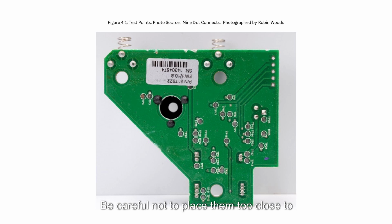Be careful not to place them too close to the solder pads of the device, because they will leach away solder from the device's solder pads. Like the lands of the footprint, the test points are exposed metal.